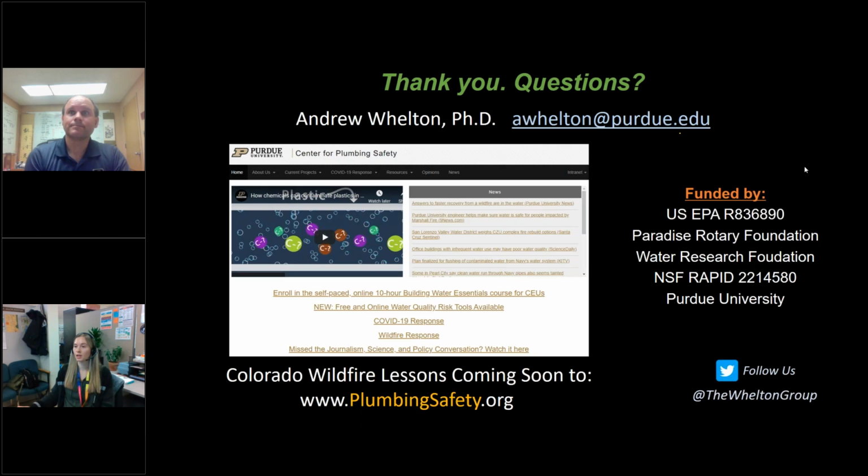Okay. Next question. If water pipes have scale buildup from water hardness, would the water mains absorb and desorb the chemical contaminants differently? That's a great question. So one of the theories we have is if you have scale, like let's say you have a high-density polyethylene pipe, but it's coated with iron because the service line is in a corroded ductile iron water system or something, and the scale is built up. If you have SVOCs or VOCs coming in, will they just interact with that scale, or will they go through that scale and get to the plastic and then go into the plastic and come out?